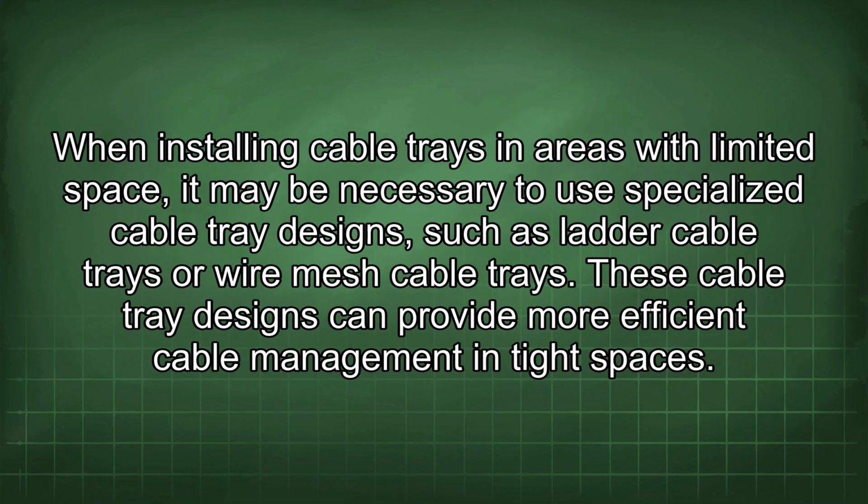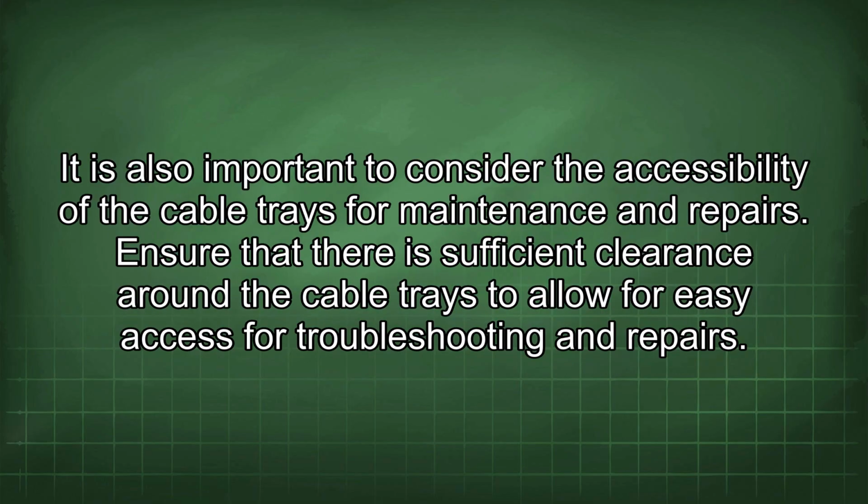When installing cable trays in areas with limited space, it may be necessary to use specialized cable tray designs such as ladder cable trays or wire mesh cable trays. These cable tray designs can provide more efficient cable management in tight spaces. It is also important to consider the accessibility of the cable trays for maintenance and repairs. Ensure that there is sufficient clearance around the cable trays to allow for easy access for troubleshooting and repairs.